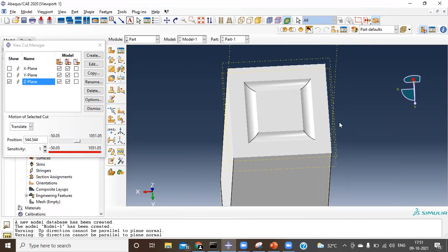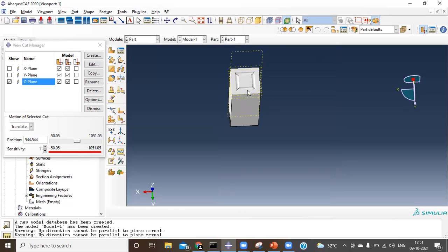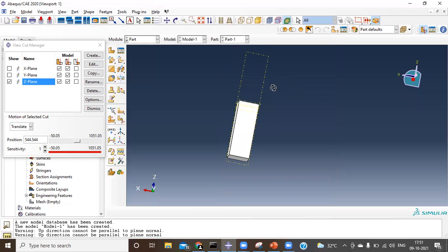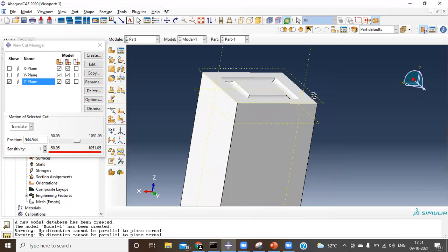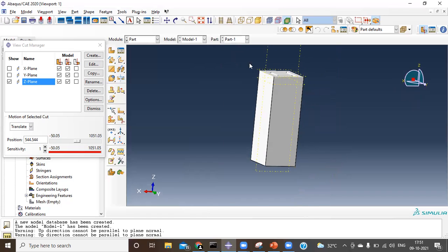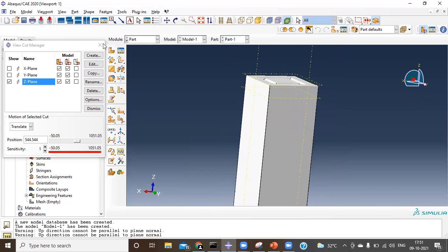With the same profile, you go create a new part with the same operations for a steel rings, and then you are going to place those particular rings over here. That's it. In assembly, that we will take care about that, okay? Only one profile that you're going to create. Let me show on that also.